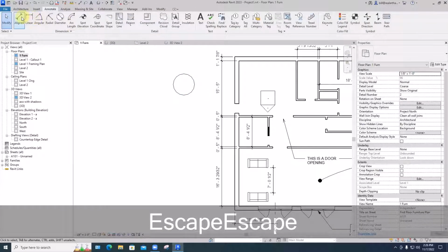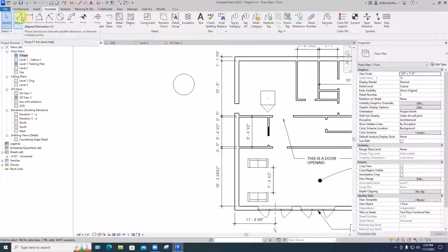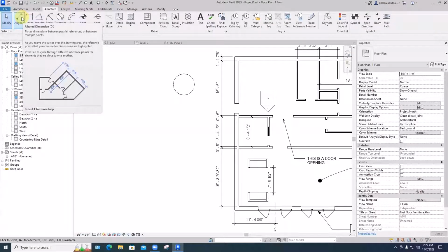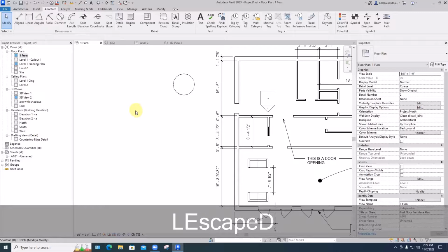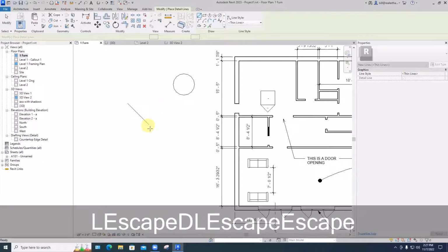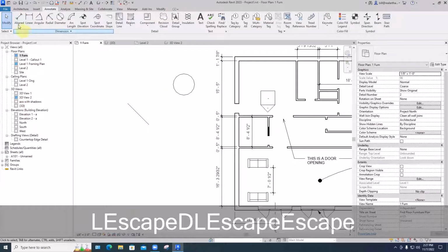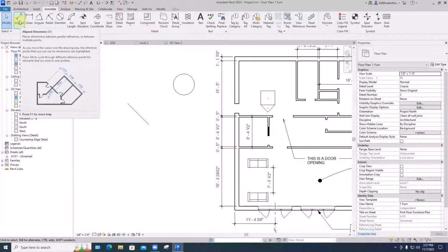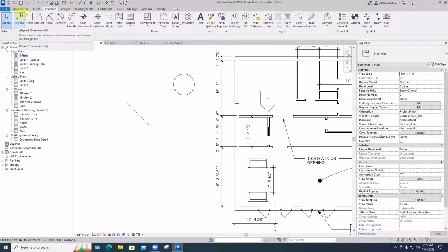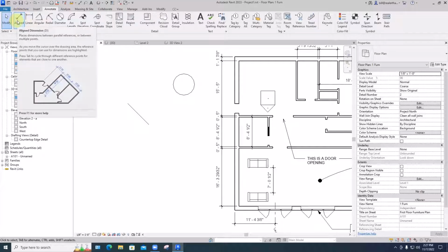So these are different types. Do we look at these in Revit? I can't remember if we looked at the different aligned, linear, that kind of stuff. Did we? Okay, fine. I'll do a couple of test cases here. Revit really likes doing dimensions between things that are parallel. And that's what you can see from this aligned button up here. We got two parallel lines.